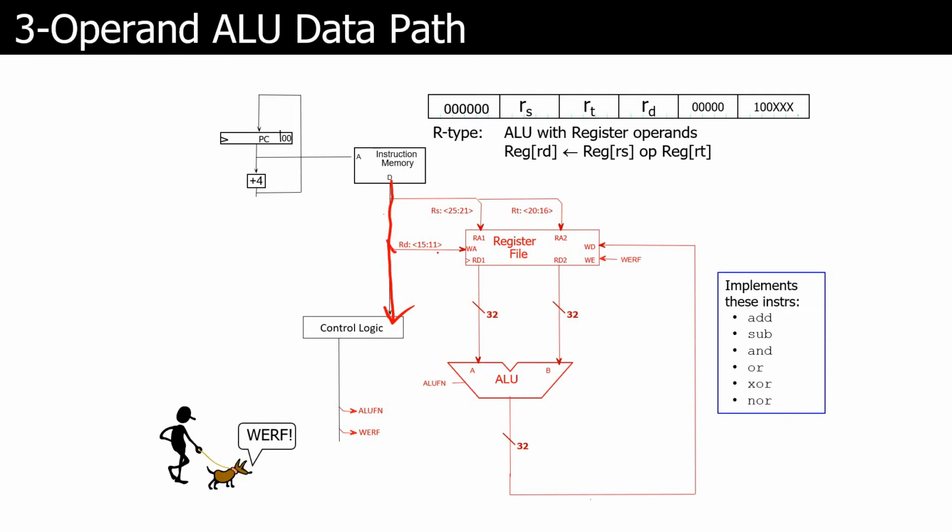And then we'll have the register values coming into the register file, each one being 5 bits, of course. And so you have RS and RT. These are your read files. RS is our source. RT is, I guess, our target. And then you have RD for our destination, which is the file that we're going to write to.